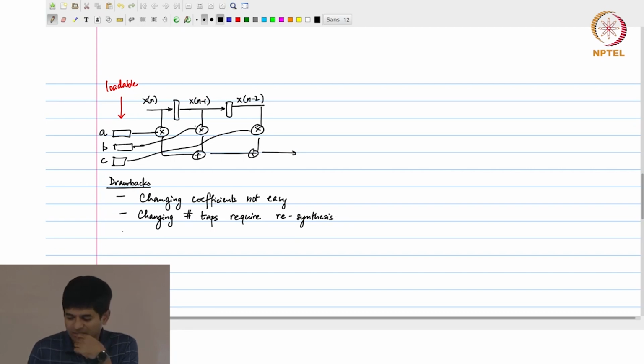And the other one is the clock and sample, these being tied together is not necessarily a good thing. It basically means that I am designing a system where even if my sample period that I require is only 1 microsecond or a few milliseconds, my clock in principle could operate at, let's say, a few megahertz or even gigahertz.